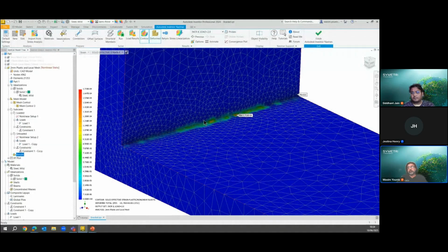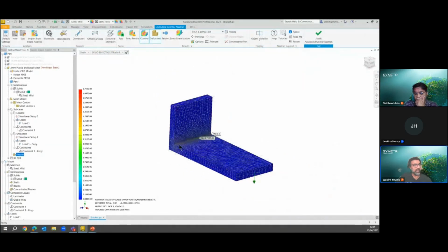So what I'm trying to say here, guys, is the high stress value you're getting, you can disregard it. So you can basically run the analysis as a nonlinear. Maybe you might want to do this, or maybe not. So if you think this is too much, then there's one more option, probably an easier option. But I think this is what refers to as localized yielding.